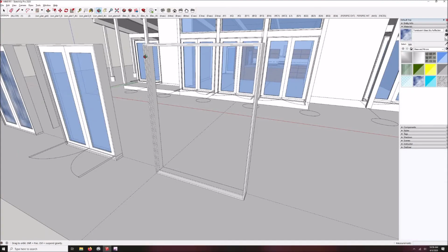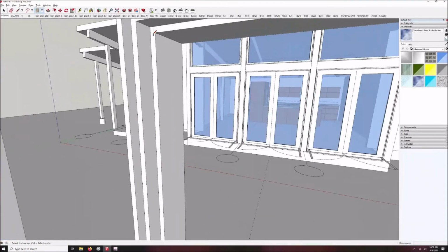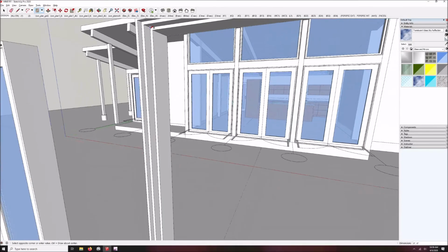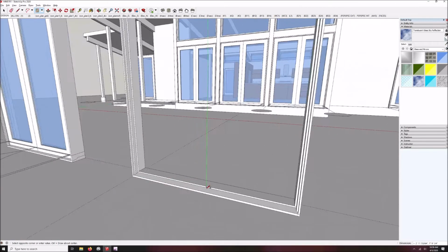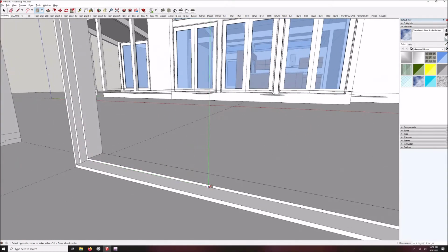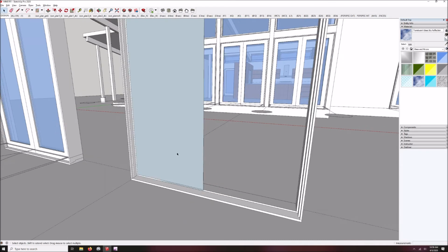We are going to make two doors, but they're going to be identical. So I'm going to start by drawing a rectangle from this top corner where the door fits in the frame, and we want the opposite corner of that door to be down here somewhere to the midpoint, wherever that is. Where's the midpoint? I just let the mouse run over that edge. It should snap to the midpoint. Okay, midpoint, great. So this is going to become my door.